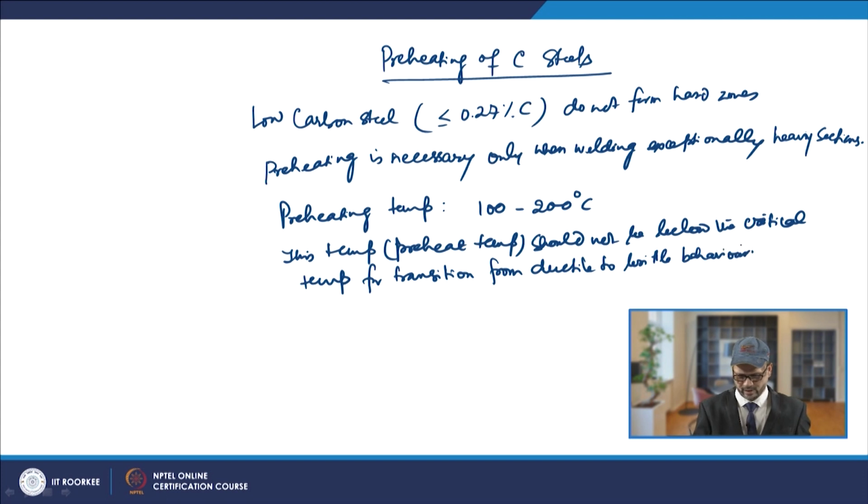Particularly, this is important when we are doing welding in the winter. We have to be careful, because many times we have the danger of cracks under the influence of these welding stress values.